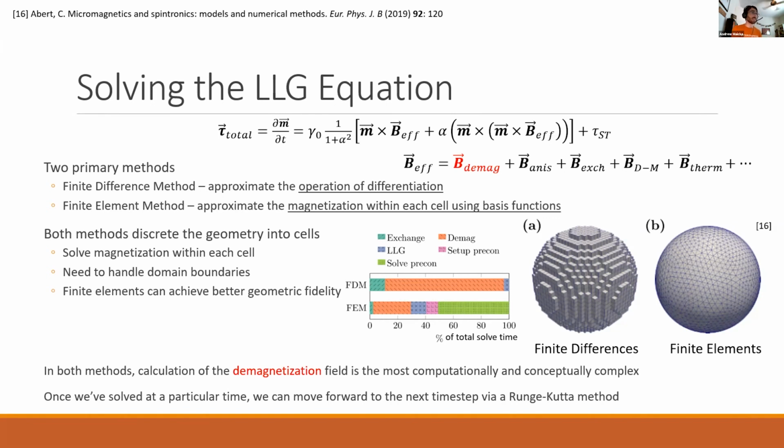Although finite elements, I think in recent years, as people have gotten newer mathematical methods and whatnot, is gaining a little bit of steam. But generally, most people, I think, probably use a finite difference method. You do get a little bit of choice over the Runge-Kutta method that you use to do the time integration at the end. But like I said, it defaults to a fourth order Runge-Kutta method. But you can go anywhere from like 1 to 6, I think, something like that.